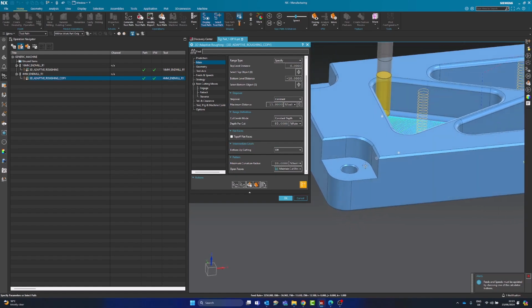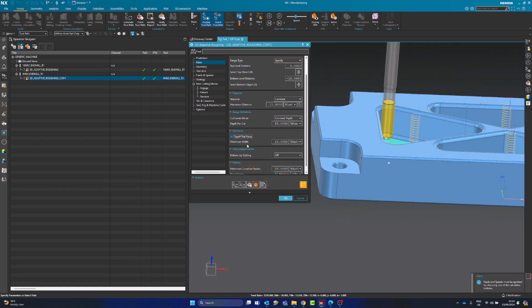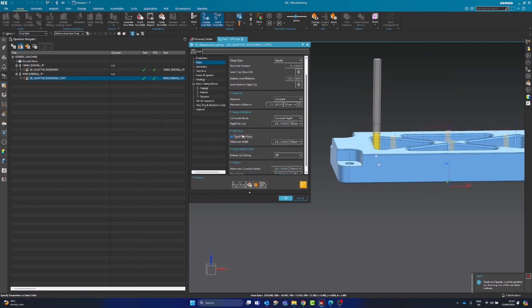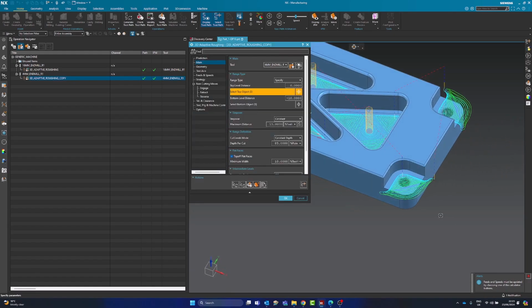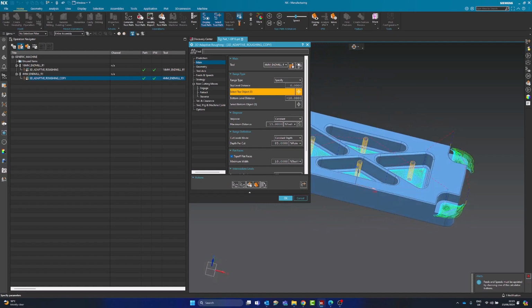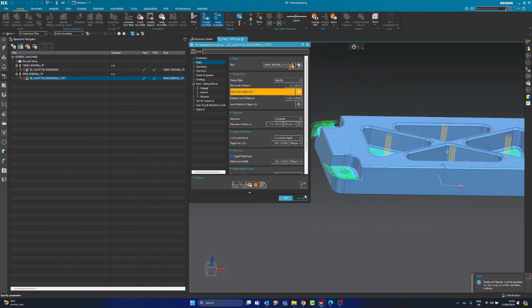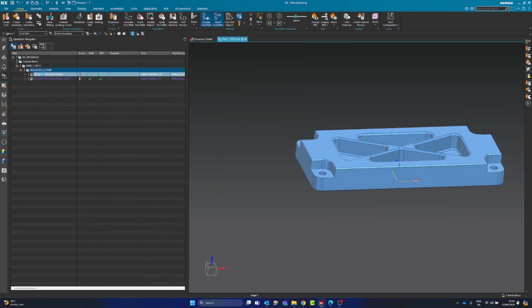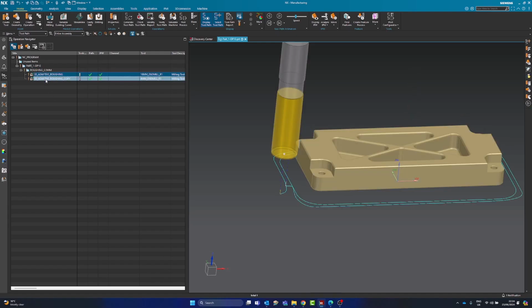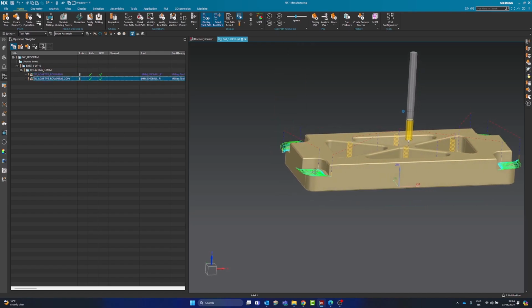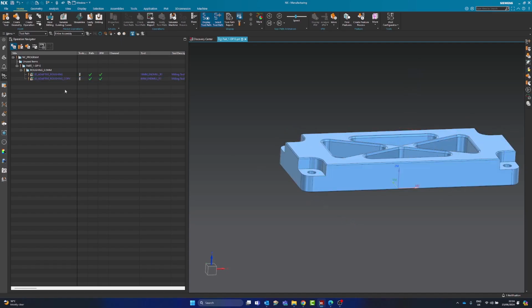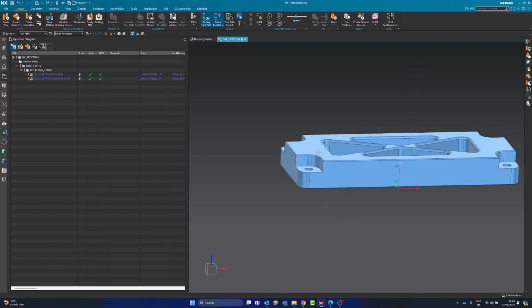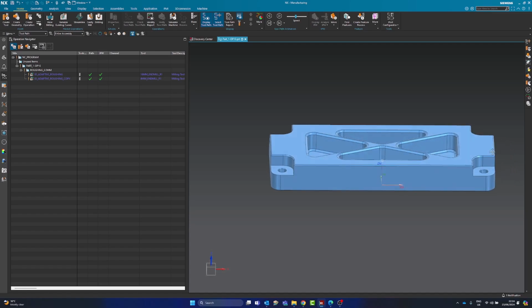So the easiest way to do that in here would be to add this top off flats. So let's add that and generate and see what we get. Okay, that's worked pretty nicely. So now we're roughing the floors and we're getting these corners in there too. So let's see what our program's starting to look like now. So now we've got 2 toolpaths in here. We've roughed the sides and we've roughed there too. So now I want to start thinking about a cut to get rid of the stock on the top face.